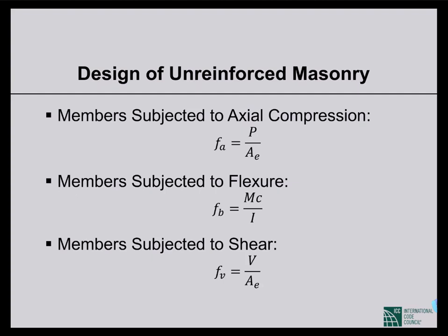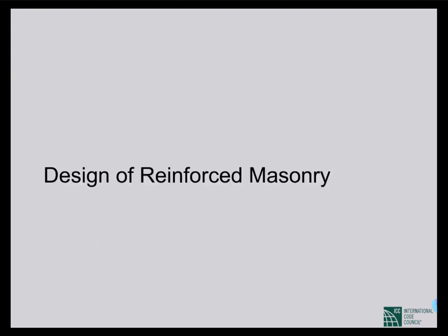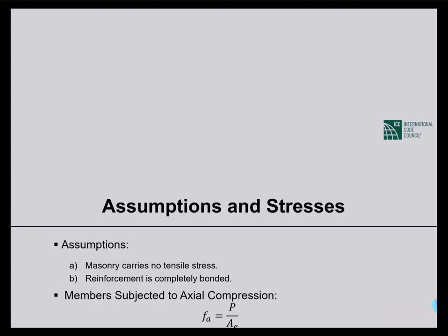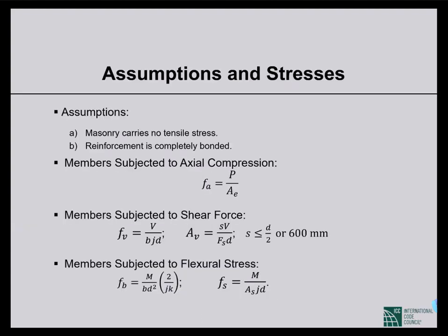Then for reinforced masonry, things are the same as what we do for reinforced concrete. Here the assumptions are: masonry does not carry any tensile stress, so all tensile stresses will be carried by reinforcement.